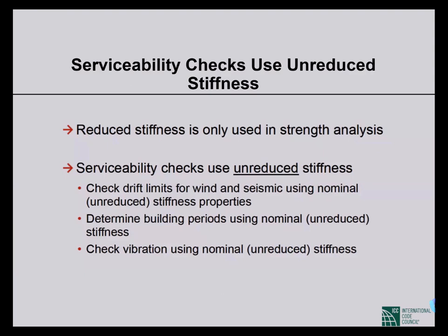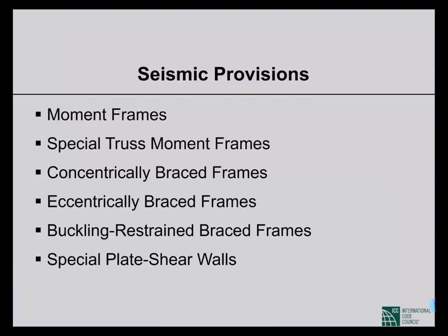And for checking of vibration, then we have to use unreduced stiffness. So that was all about the direct analysis method. In some of the software, the direct analysis method is already incorporated, like SAP. You can find the direct analysis method there. And I think there are user manuals, some manuals where you can learn how to use SAP to apply the direct analysis method.